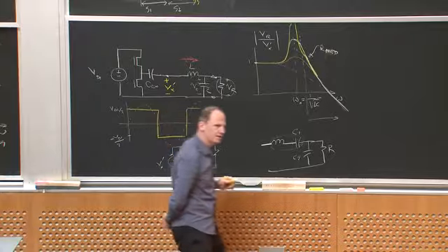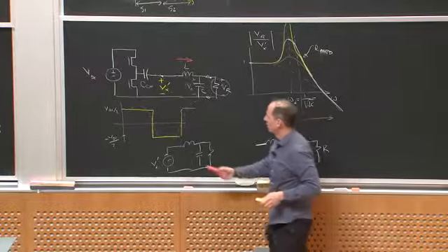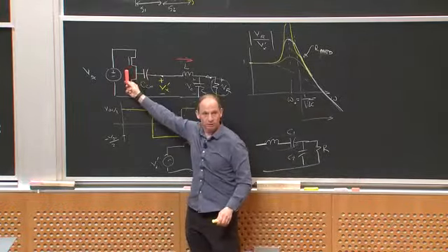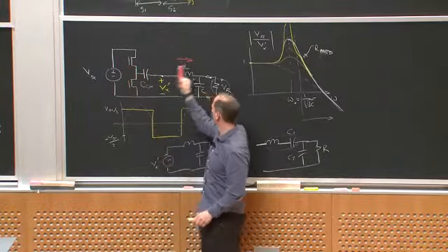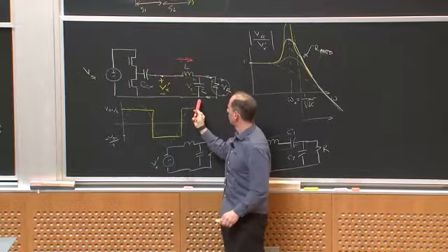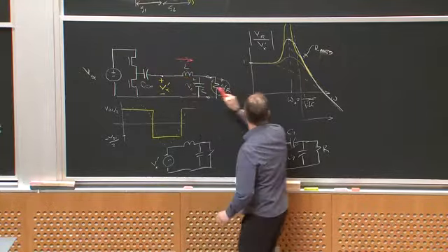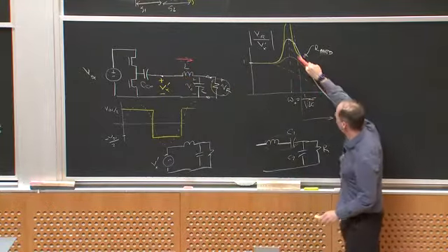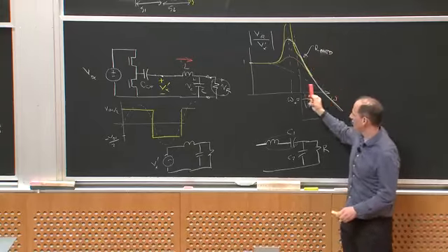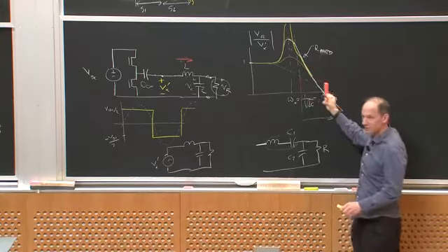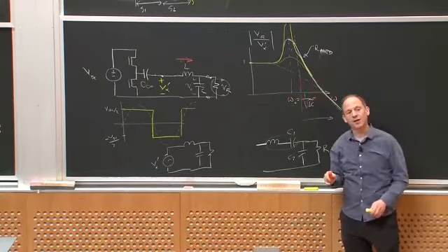So how would I build a DC to DC converter? Well, maybe I'll use an inverter, create a square wave, use a high Q network to extract a sinusoid, and then I can use that to control voltage gain, right? Because I can control the amplitude of the current by varying frequency. And then I just run into a rectifier.